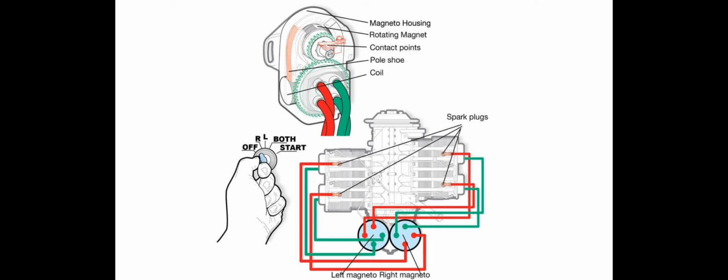What is the proper spark plug reach? The electrode end is in the best position to achieve ignition inside the cylinder. Why is it important to keep track of the cylinders that spark plugs are installed in? Spark plugs can provide information on the health of a cylinder.